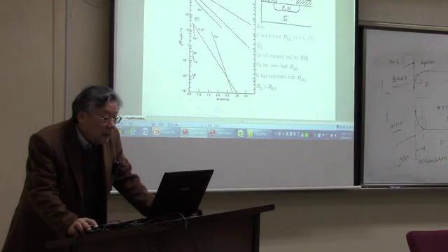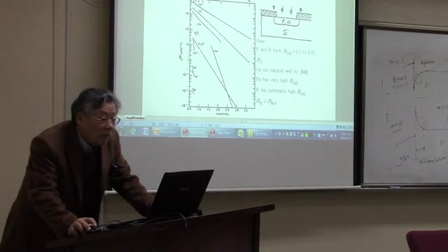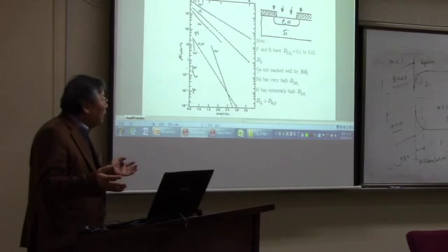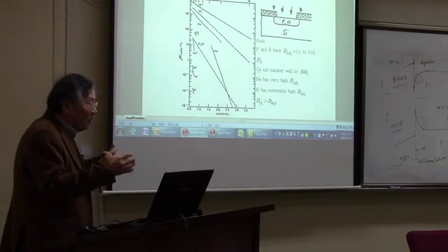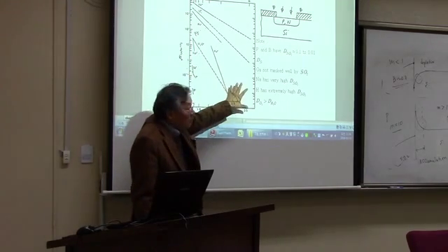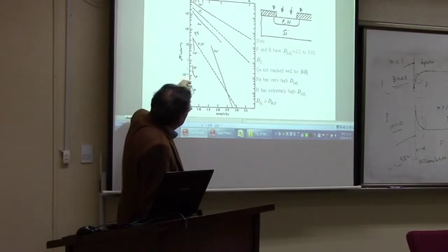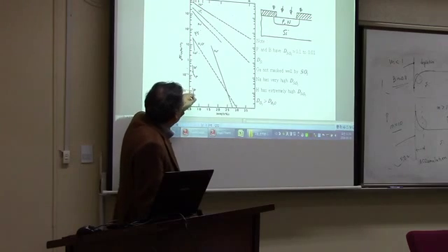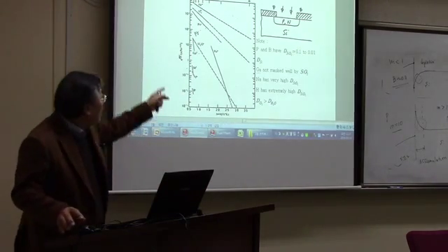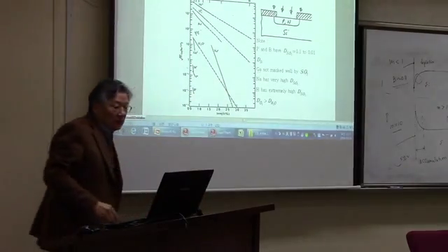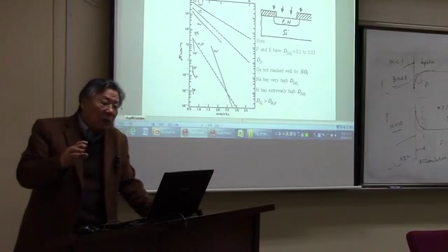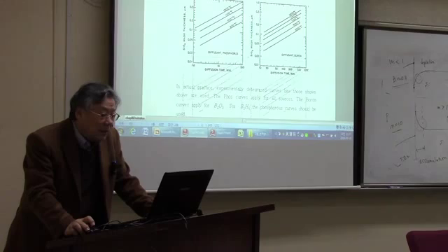All right, let's move on to the masking properties. And this is the phenomenological thing. We can do the calculation by knowing the diffusion coefficient of the impurities in the oxide, but it's a very complicated equation we have to solve. This is just a phenomenological observation. Now, sodium is very fast, and hydrogen is even faster than sodium, okay? The gallium is relatively fast, something like that. The hydrogen, you can see, has a very high diffusion coefficient in the oxide. So these elements are not going to be masked by the silicon oxide.